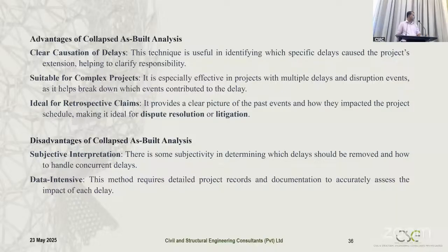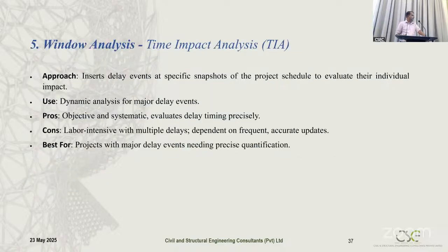And ideal for retrospective claims. So we are dealing with as-built data, which is good for later claims. The disadvantage is that it is subject to interpretation. We are dealing with as-built data, so if things have not been properly documented, we face some problems. This method requires detailed project reports and documentation to accurately assess the impact of each delay. If we don't have proper reports, we cannot perform this method.